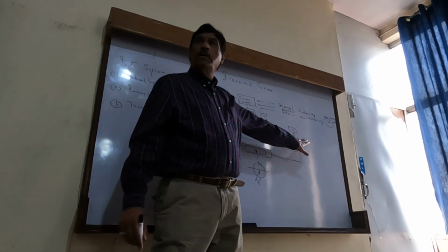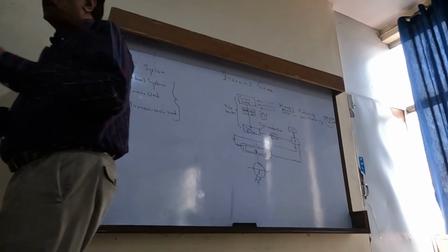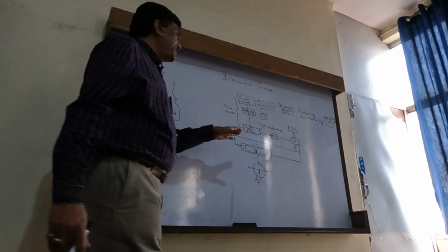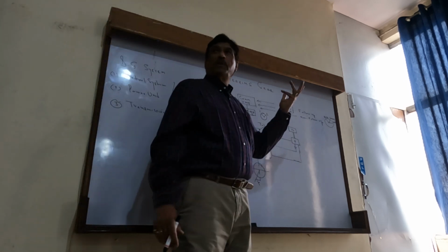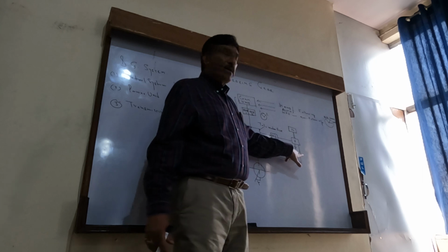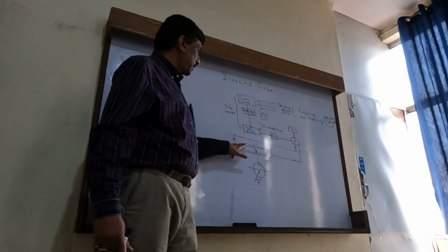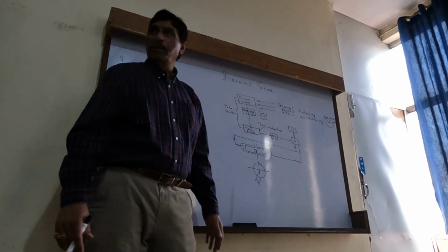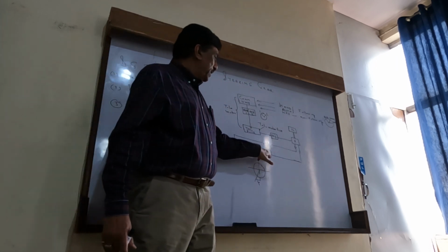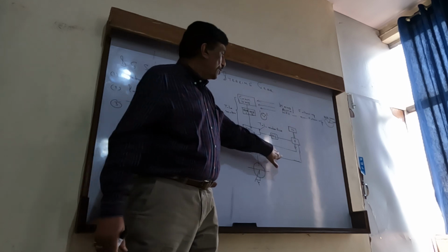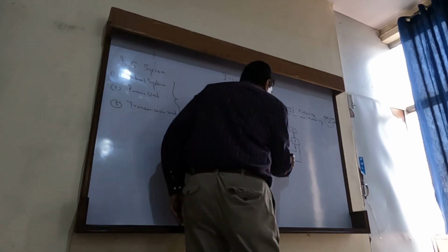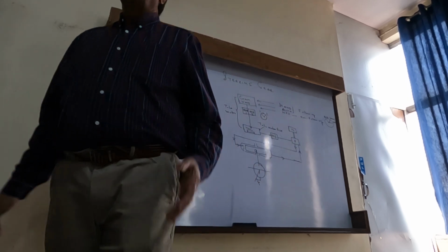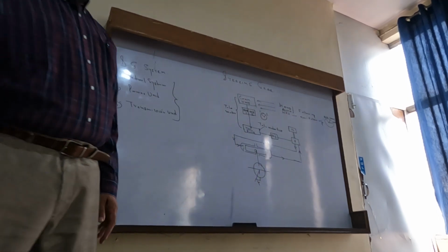This is the pump. So the pump has discharge and suction, two lines, which is same for any pump. Let us say I want to give a port movement. Then the oil should come from here. High pressure oil coming here, acting in this chamber, will push the ram towards right. Whatever oil was there originally will go back to the suction side. Therefore, this side is like this. That is the return.